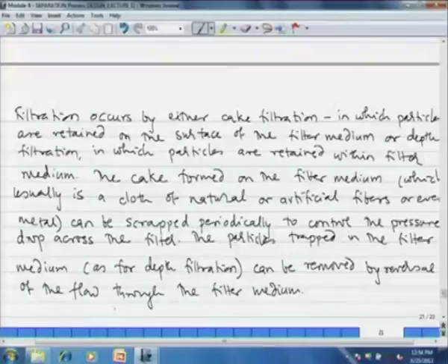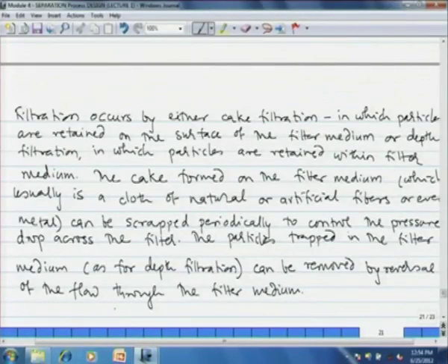The high boiling components like benzene, toluene, diphenyl condense, hydrogen and methane are left out, and then the separation of the benzene, toluene and diphenyl is achieved through 2 distillation columns. And for the gaseous mixture, we have to go for purging, so that the methane concentration does not build up beyond a certain limit, and then part of the gas is recycled and part is purged.